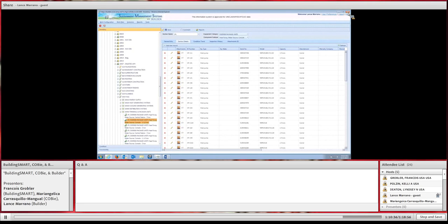If it's a complex piece of mechanical equipment like a rooftop unit, and you are just replacing a fan motor or a condenser, that might now be defect free, but the other things might still have problems. You may still have rust on the enclosure. You may still have fan belts that are starting to age and harden and crack a little bit, but not enough to need repair. So it depends on the situation.